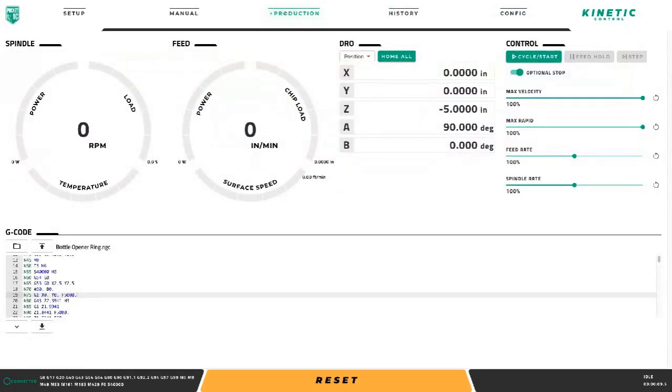There's a couple questions about the gauges, so calculated value, and then Mark just asked, based on program parameters or sensors. Yeah, so the sensor values are calculated. So this one isn't based on sensors, but just based on where the position of the machine is. It knows instantaneous rotational velocity and instantaneous linear velocity, and calculates an instantaneous feed rate of the tip of the tool. So that's what this value is in the feed gauge.